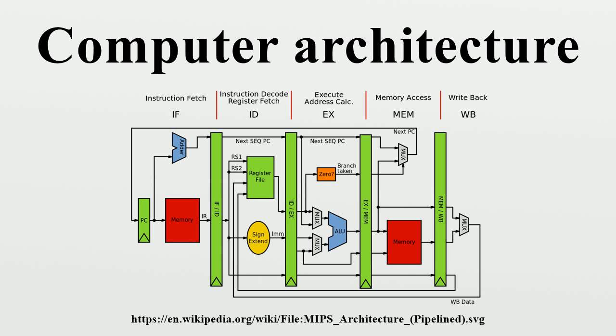Implementation. Once an instruction set and microarchitecture are described, a practical machine must be designed. This design process is called the implementation. Implementation is usually not considered architectural definition, but rather hardware design engineering. Implementation can be further broken down into several steps. Logic implementation designs the blocks defined in the microarchitecture at the register transfer level and logic gate level. Circuit implementation does transistor-level designs of basic elements, as well as of some larger blocks that may be implemented at this level, or even at the physical level, for performance reasons.